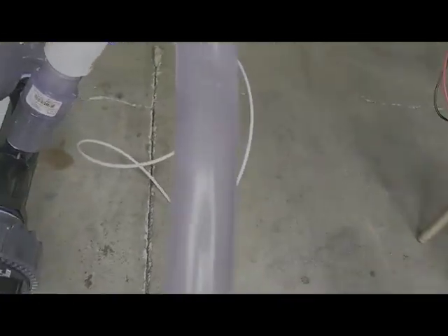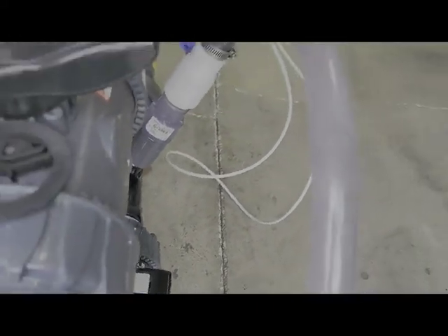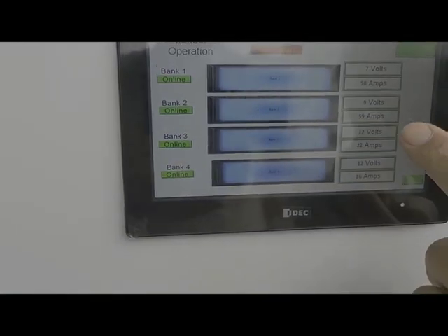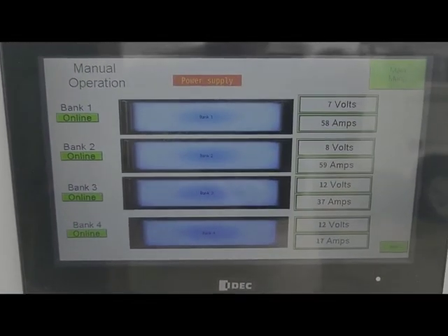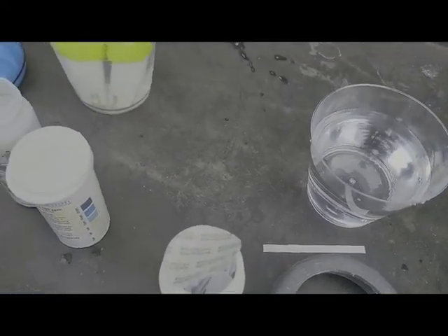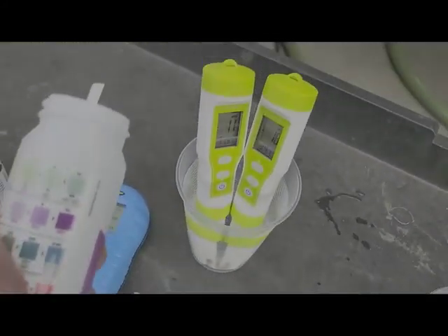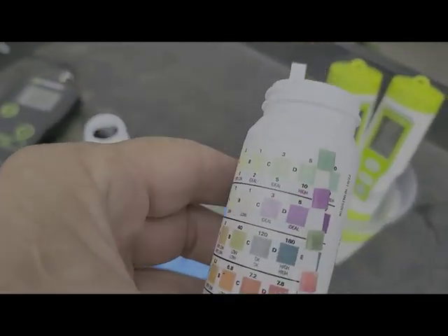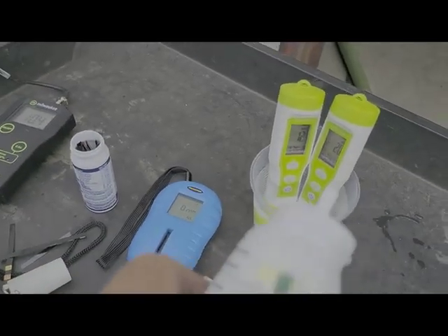And as we inject it through this slurry, the chlorine is being produced at a very high level. There it is, about 350, 400 watts per power supply. So about 2.5 kilowatts total. So this is the chlorine, free chlorine, and chlorine measurements.